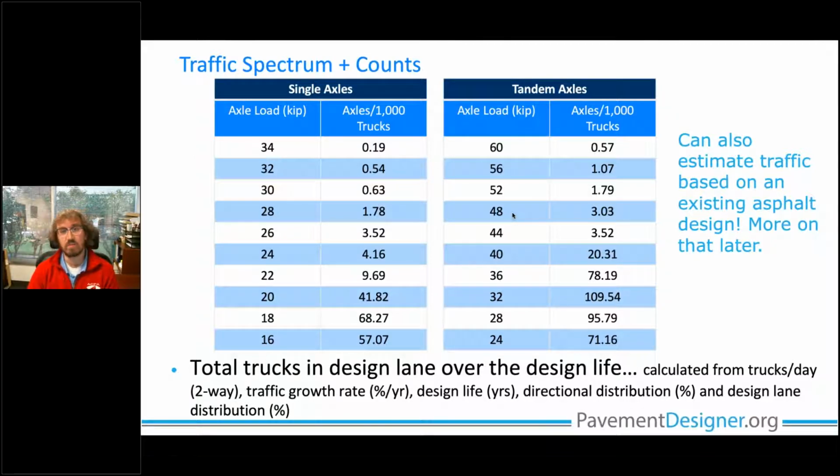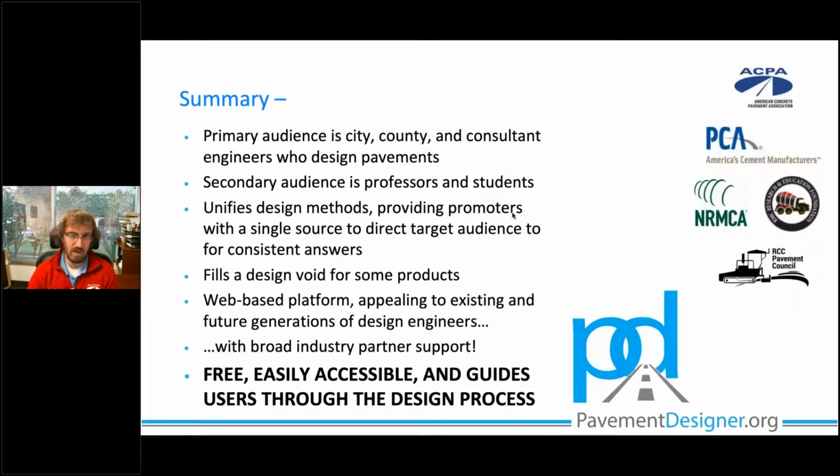And so one of the last big leaps with Pavement Designer is that we're actually looking at load spectra. This is a big jump from AASHTO 93 because we're not estimating traffic in the form of ESALs, or equivalent single axle loads. We're actually designing based on the number of trucks our pavement is exposed to. You'll see how this is incorporated into Pavement Designer in just a second when we look at the program. But it's important to know that load spectra is a great big jump from that ESALs design of the old AASHTO design methodology. Additionally, load spectra is how PavementME designs for concrete pavements as well.